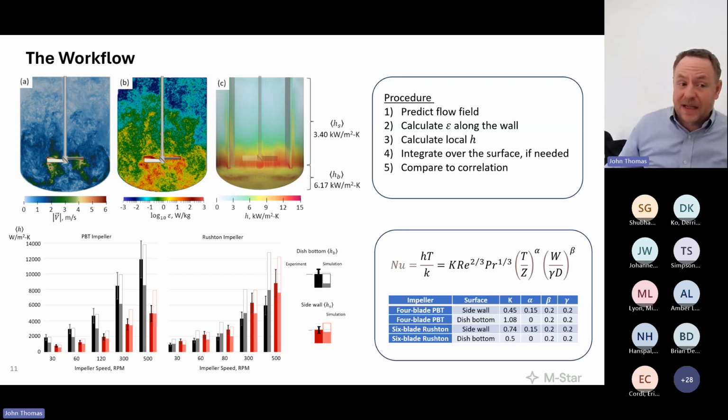So they're going to have very different total convective heat transfer coefficients, or Nusselt numbers, I should say, because they have very different interactions with the trailing vortex. And what I can see here is using a few different first principles models. Now I'll talk about later which one's best, because there are some arguments over which cofactors are better based on what semi-empirical theory you appeal to.